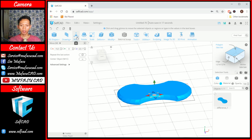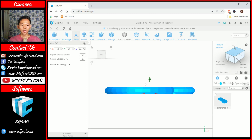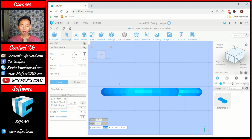We can move these objects to the top. And for handle I will change into front view, and in here I will use 3D sketch. We can change the plane settings in here into back to front. I will use back to front, and then I will use this line tools. I will create handle like these models. I will move to this point. These are 4 handles.